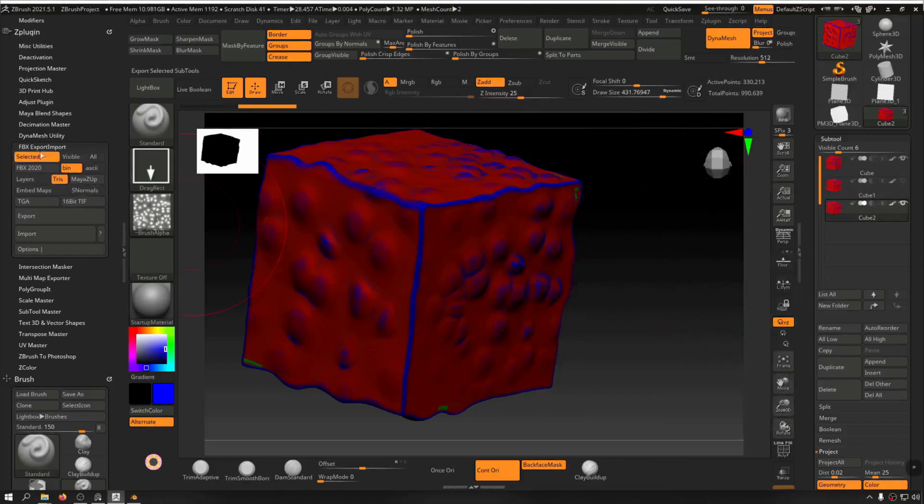But now we are going to use only selected, which is this one, which has been selected using this color that you see here. And for the version, you simply put it in here and you want to set it to binary. And then you want to hit triangulation on, and this triangulates the mesh for you, and then you can export that.